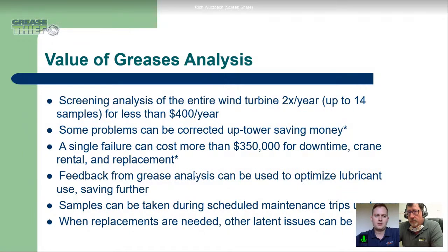Vibration condition monitoring does detect main bearing issues, but oftentimes it's a little too late to take as proactive a measure as a hot oil flush on a main bearing. Right, because at that point you've already got some physical, mechanical damage to the surfaces before it's going to show up as vibration. Yeah, you have asperities, indentations on rollers, inner and outer races. You're generating more and more wear debris as that continues on. So the key is to get ahead of that.